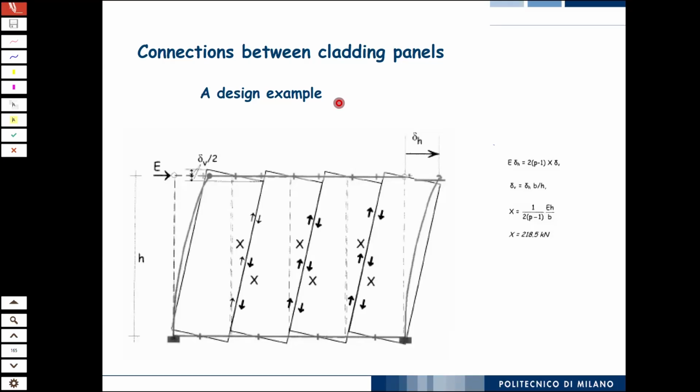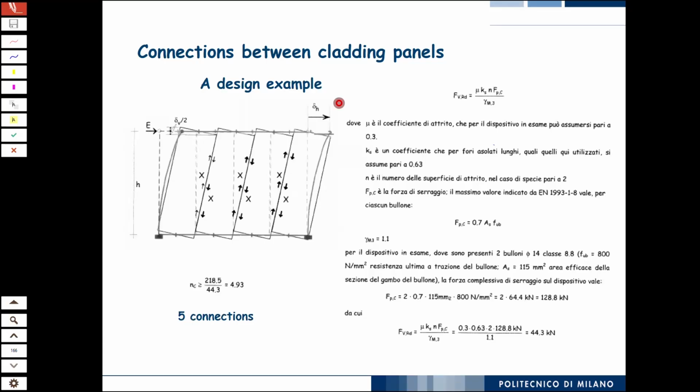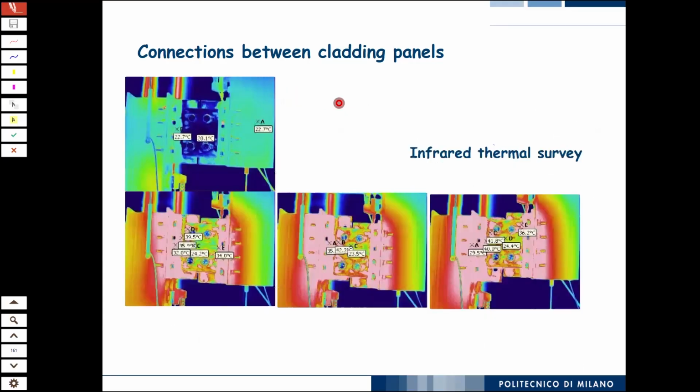So you can easily calculate the force that is asked, according to the earthquake, of each of these devices, and how can you obtain it, considering that this force is the friction coefficient times the number of connections times the tightening force that you give to the bolts, divided by a safety factor. And so this was quite a simple example that we developed.